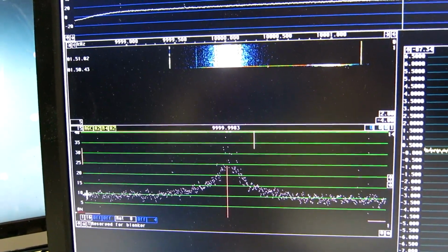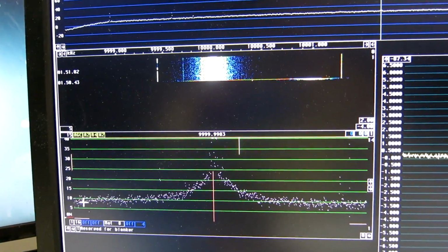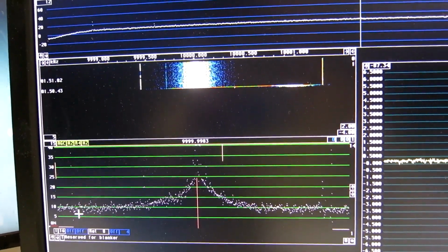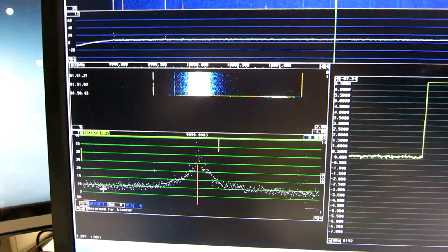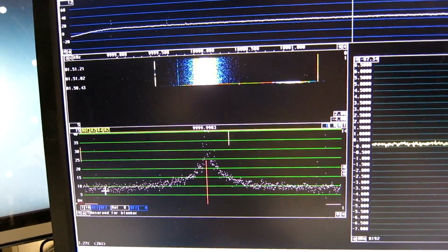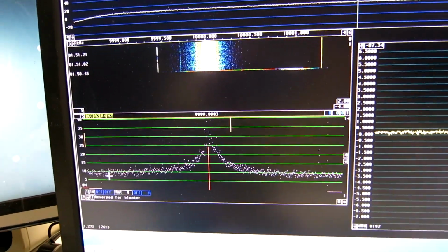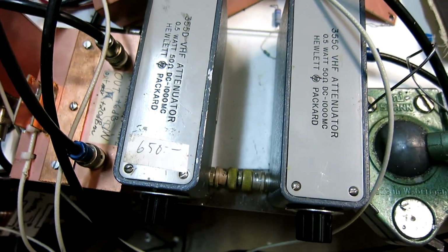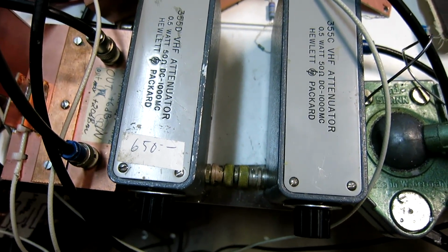We see the thermal noise of the crystal, but off resonance the crystal is a capacitor or an inductor with a low impedance, and that doesn't give any noise. That's the basic idea of getting very low sideband noise in oscillators.